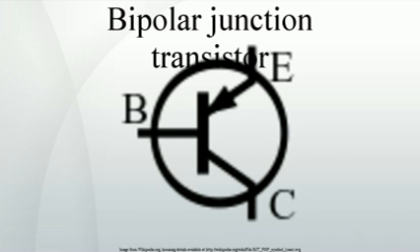Amplifiers. The transistor parameters α and β characterize the current gain of the BJT. It is this gain that allows BJTs to be used as the building blocks of electronic amplifiers. The three main BJT amplifier topologies are common emitter, common base, and common collector. Temperature sensors. Because of the known temperature and current dependence of the forward-biased base-emitter junction voltage, the BJT can be used to measure temperature by subtracting two voltages at two different bias currents in a known ratio.